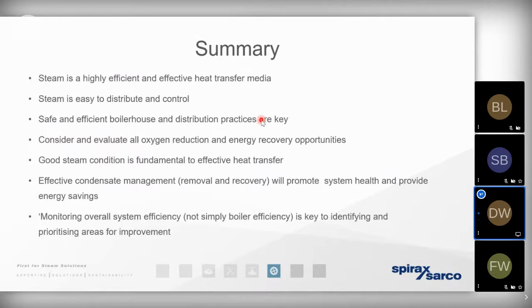Typically, we would do that immediately behind the steam boiler itself. But as far as the distribution network is concerned, we also want to be using separators ahead of sensitive equipment, such as control valves and flow meters, and immediately before it enters the process. But please remember that the biggest enemy of a steam distribution network is wet steam.